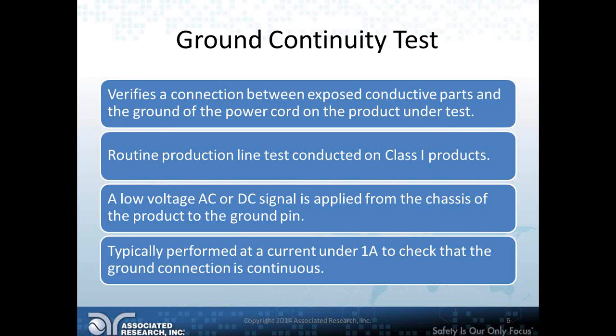Grounding electrical equipment provides a second line of defense against electric shock over and above the basic installation of a product. This grounding of the metal enclosures or exposed dead metal on the equipment also establishes a common ground or earth reference between multiple pieces of equipment which may be in close proximity to each other.